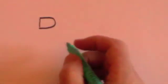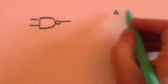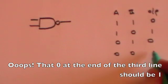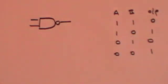And you can get the reverse of all these things. You can have what's called a NAND gate, which means a not AND gate. And it looks a bit like the AND, except you put a little circle here, and that makes it a NAND gate. And the idea here is that it's precisely the opposite of an AND gate. So if you get positive inputs on both channels, you get nothing on the output. It's NAND, it's not AND. On the other hand, if you get a positive input on one but not the other, you do get an output. And indeed, if you have no inputs on either, you do get an output. A NAND gate means you get an output for everything except where it is an AND. It's a not AND gate.